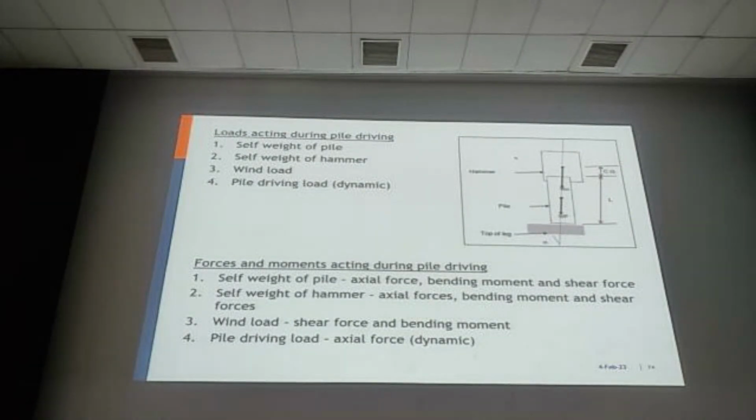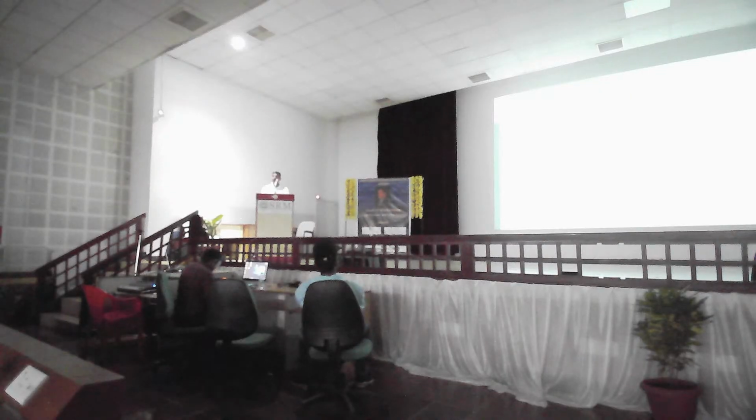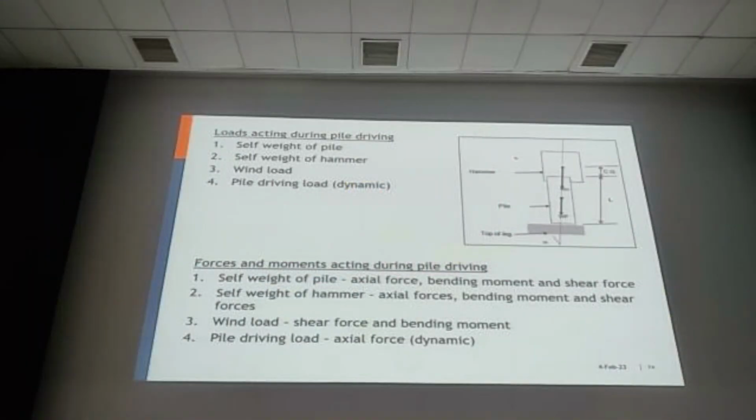So in pile drivability analysis, you have to consider the self weight of the pile, the hammer, even wind load, and pile driving load. All this will act on the pile. Make sure that our pile is safe for that. You need to provide sufficient thickness. Anyway, if you provide higher thickness everywhere, then again it is a task how to lift it and how to place it on top of the jacket.